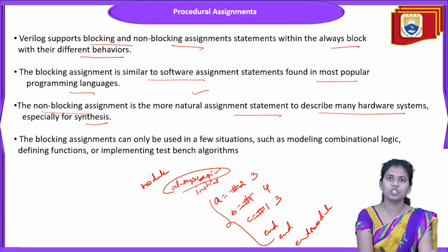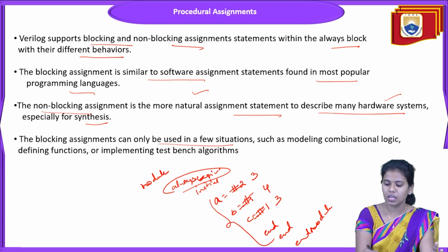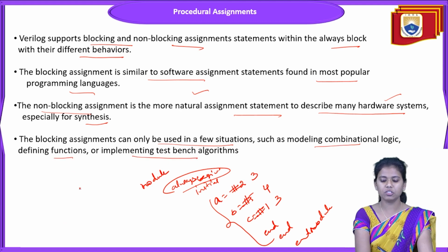For synthesis and simulation purposes, the non-blocking assignments can be considered prominently, usually for describing hardware systems. And the blocking assignments can only be used in a few situations, such as modeling combinational logic, designing functions, or implementing test bench algorithms. So for the blocking assignments, only situational purposes we can use them.